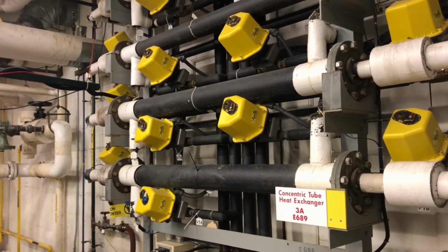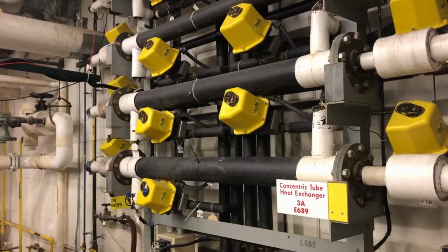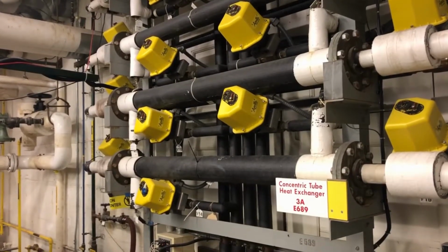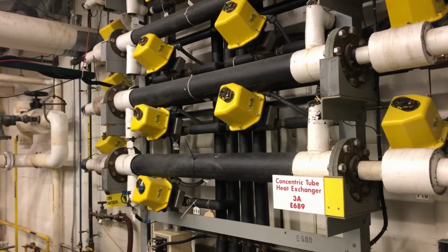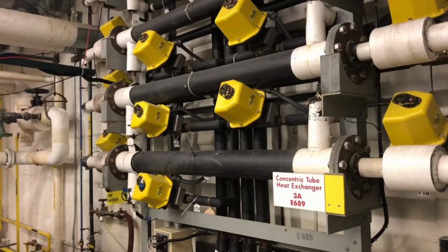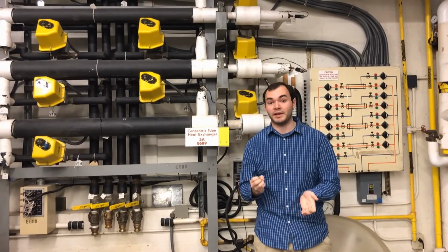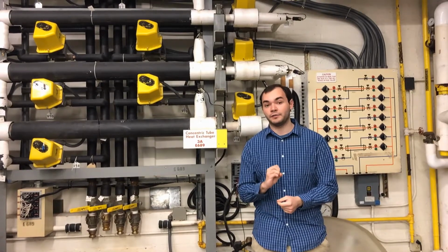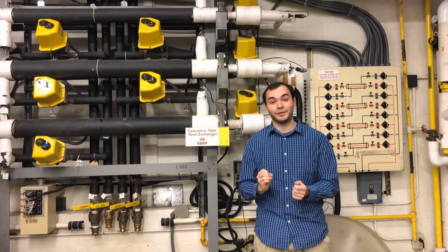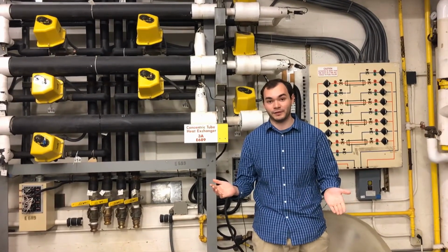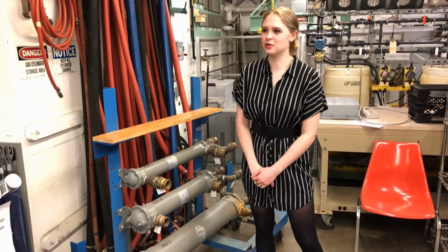First, we'll start with the most basic heat exchanger design, a concentric heat exchanger. It's incredibly simple. One fluid passes through a central pipe, and another passes through an annular space between that and a larger pipe. This is a design that's quick to set up and easy to size. These are extremely simple to design and to install, as well as to repair and maintain, but they are very inefficient. They pay for the price of their simplicity by basically losing up to 80% of the efficiency that you can have.